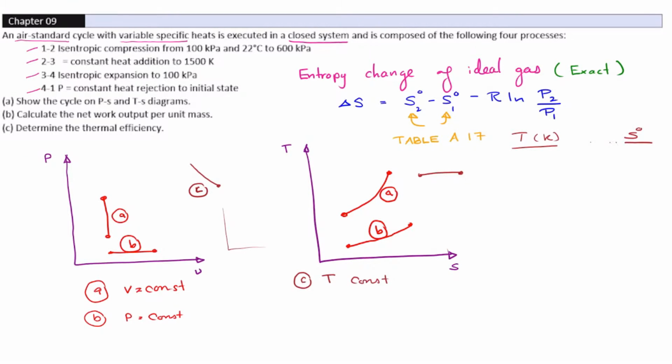The reason is, in PV diagram, we draw our constant temperature lines as slightly diagonal lines on the gas region. If it is a constant entropy line, it is going to be a slightly curved diagonal line on PV diagram. On the TS diagram, it is going to be a vertical line. Now let's try to draw these processes on PV and TS diagrams.